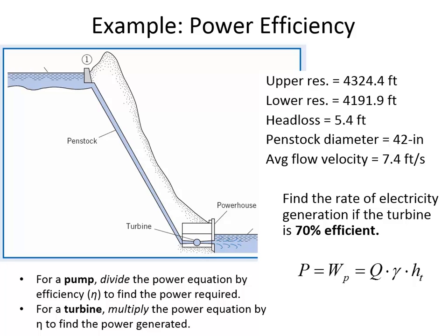D would be feet because that's a length property. And then G is feet per second squared. So the seconds cancel out. These 2 feet go away, and we just have feet left over. So that's a way of expressing that head loss is pipe friction, and it can be expressed in terms of a length parameter.